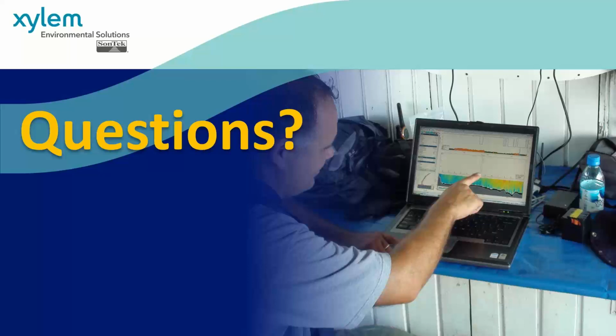With the acoustic signals, if you have too much sediment, the acoustics won't propagate through the water, and so you're not going to get a return signal and velocity. But vegetation usually tends to absorb the acoustic signal more than hard grains of sand, for example. So it really depends on what's in your water and the ratios of that sort of thing.